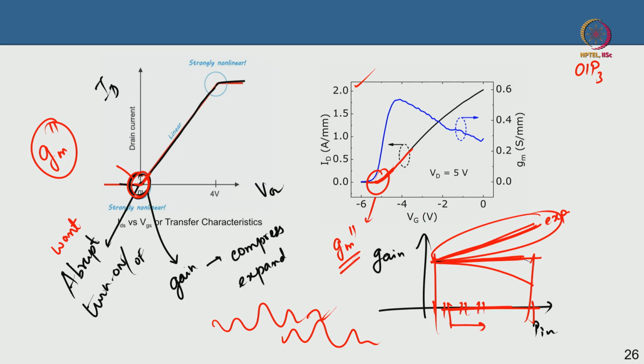That is how the device is, and that is what people have to consider when they consider the linearity aspect of the device. But the important thing to understand here is that the drain current does not increase linearly with the gate voltage, and that is why when you take a derivative of the drain current, which is the transconductance, you see that the transconductance has a peak. This peak by the way corresponds to peak Ft also, and after that the transconductance falls off. This is called your GM roll off, and I will show that this is a very significant and critical issue in the linearity of gallium nitride HEMTs from a device perspective.